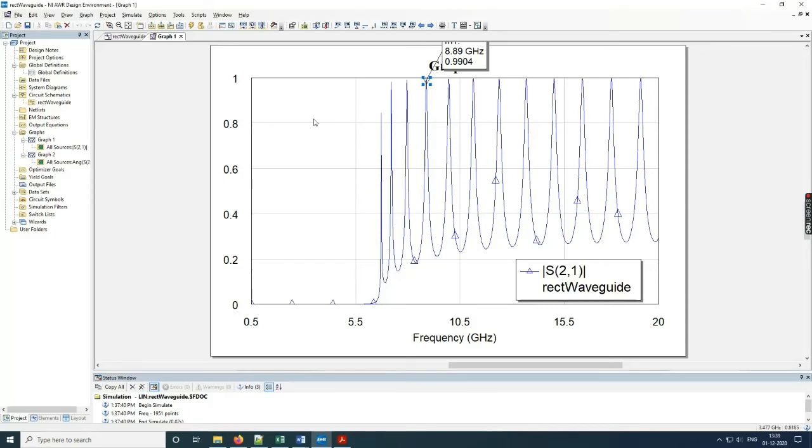Now, if I were to input some signal which is a non-sinusoidal wave, let us say I am feeding one wave whose base frequency is 6.73 gigahertz. And there is also one more signal component which is at 7.21 gigahertz. Now, let us see how the dispersion actually happens. So one is 6.7 gigahertz, the other is 7.21 gigahertz. For a dispersion-free transmission, the system should have a linear phase response.